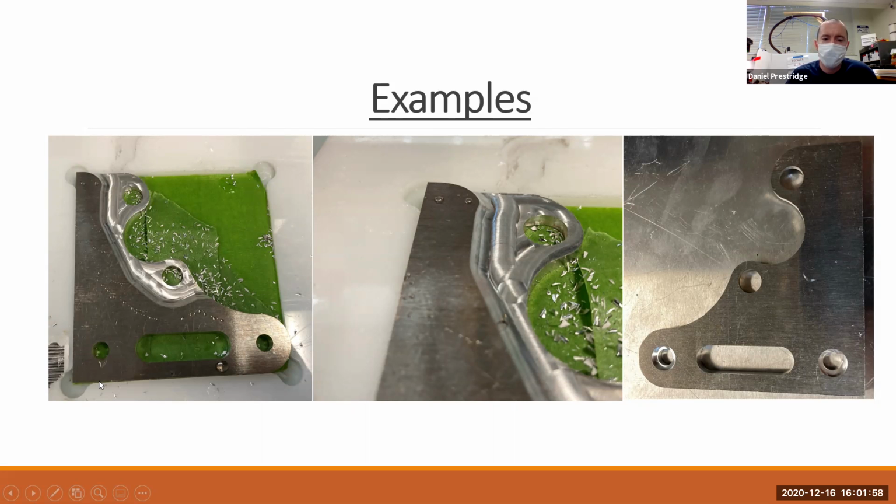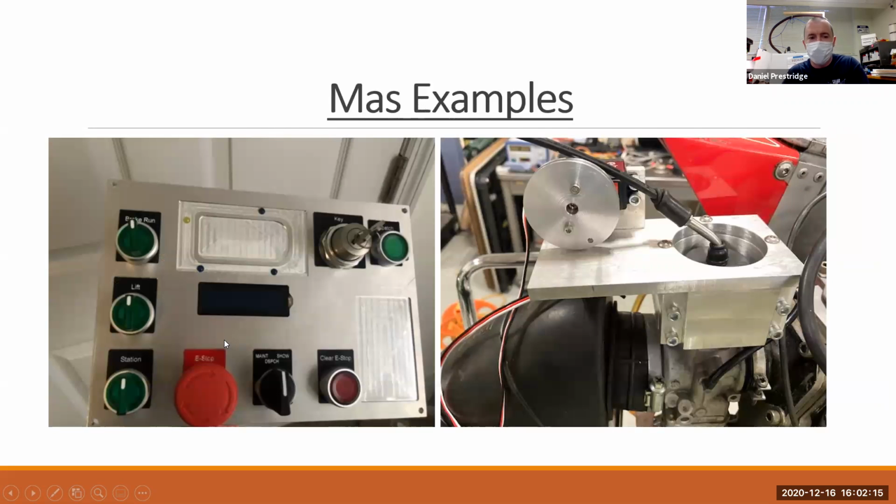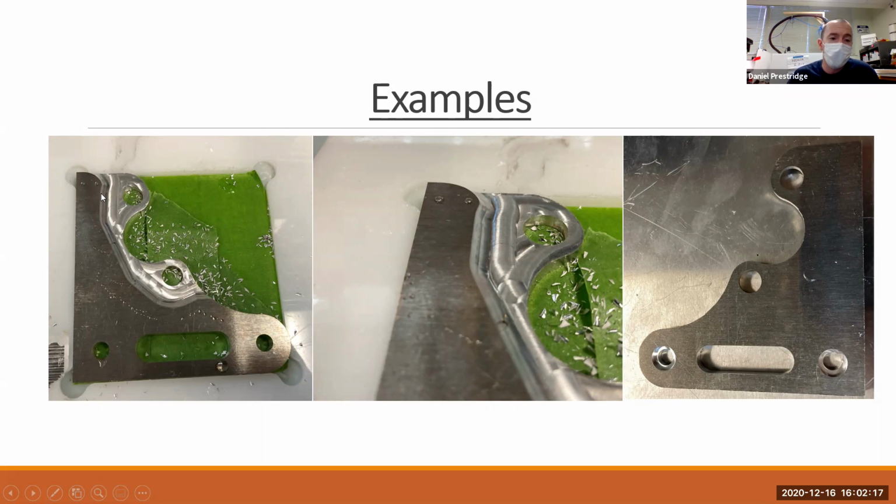So I saw this trick on one of the websites that I'm going to recommend called NYC CNC, and he cut the corners out of it as one of the operations, and then this lets this sit into this corner without having to worry about a radius, which turned out really well.